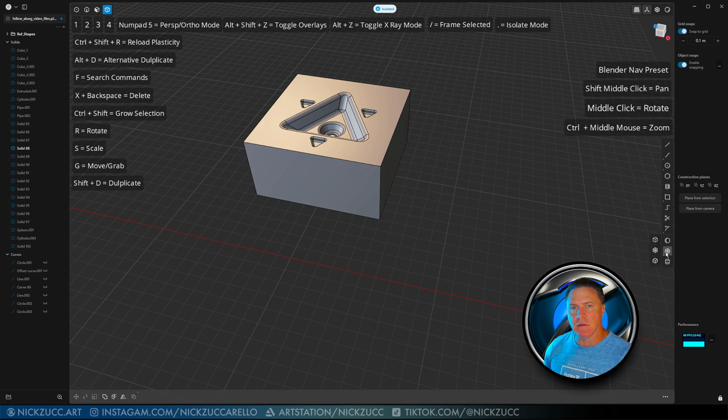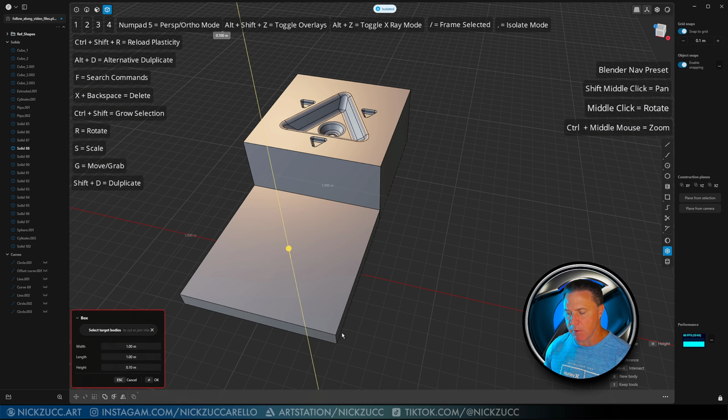This time I'm going to use this box and I'm going to use the center box. I'm just going to click and drag out from my grid and get my grid snap turned on. Just going to click and drag out. And what I did notice about this is if we get into this corner really close, you can see it's going to click on this tangency purple line, and I don't want that. I do want it to snap to the grid, so if I just move my cursor just a little bit right here or in this area, you can see how it's going to now snap up to that.